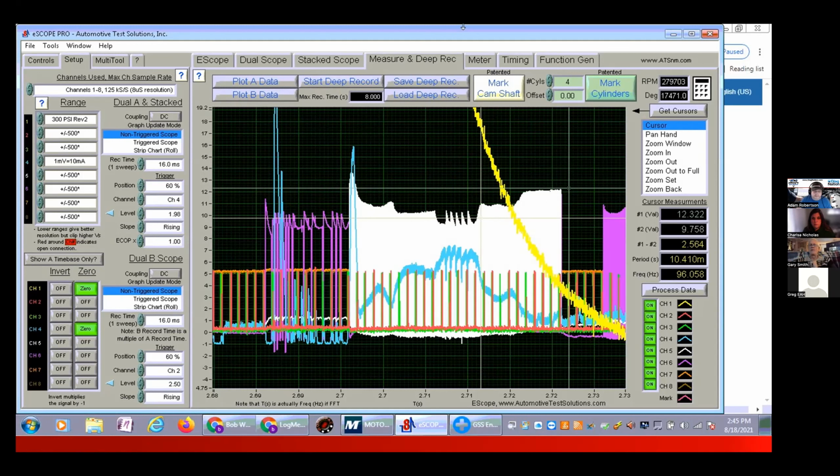What I found out from reading the data sheet description is that when that under voltage or any of those four faults occur, under voltage, undercurrent, over voltage, overcurrent, or the temp faults, this will go into a default. When it drops the throttle motor out from under your foot, for example, the very next thing it does is try to reboot itself. That's the activity that we're seeing here.